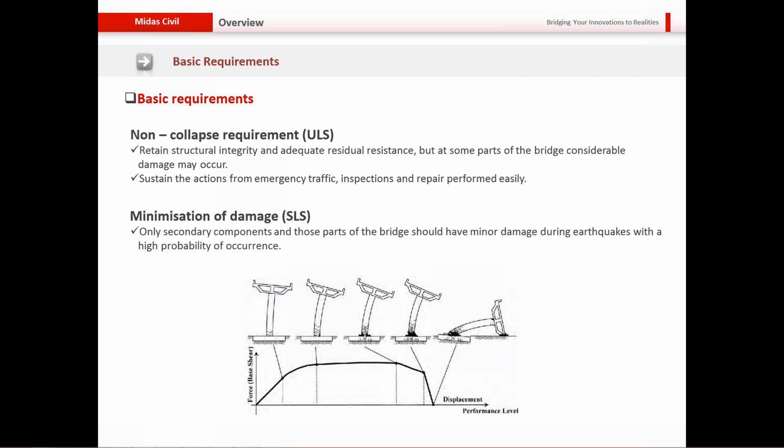The SLS requirements are usually along the lines of damage minimization. That is, only non-load bearing or secondary components of the bridge should sustain any damage, if any damage is indeed required to be sustained.